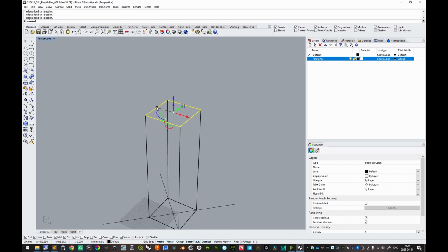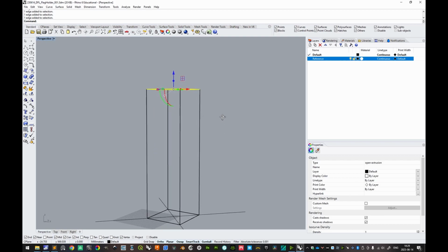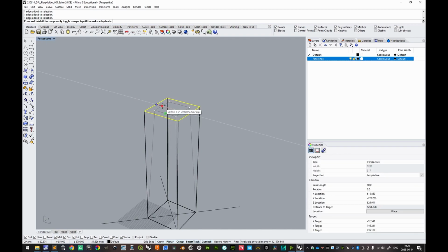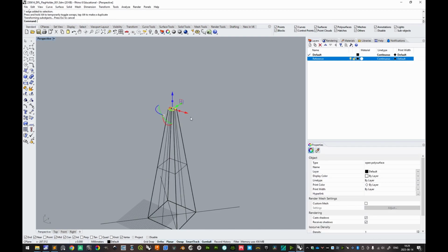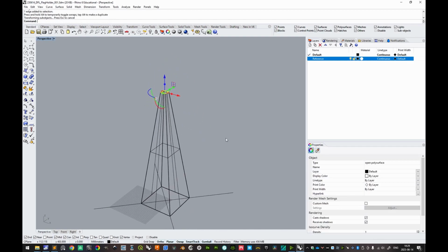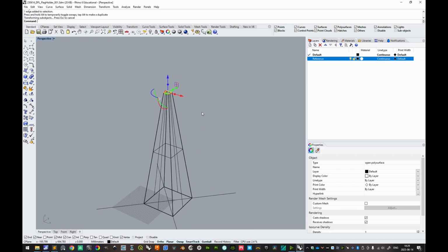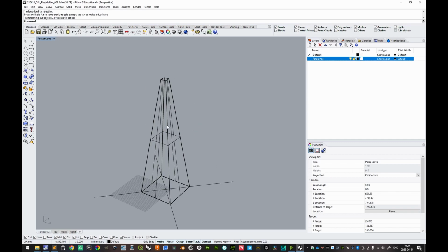and then do the same as you did with the reference lines for the symmetry. So we'll hold Shift to make sure that the scaling is uniform, and since the object itself is flat in the Z direction, then it will only scale in the X and Y direction. So we scale this and make it smaller. If we hold Alt, then we can temporarily disable the snapping as well. And perhaps like this. It's good. And now you saw that we changed the properties of the 3D object here so as to more conform to our intended design.